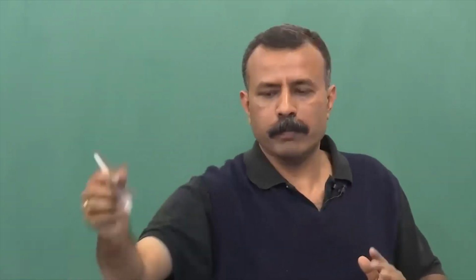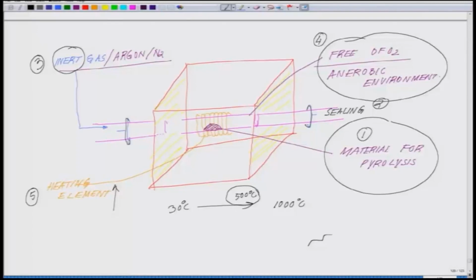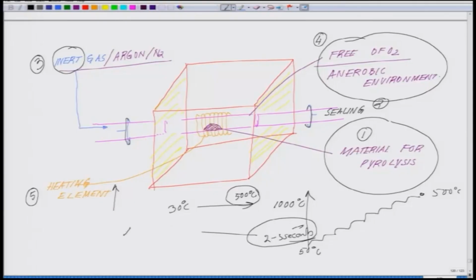So, exactly similar to that, you can really jack up the temperature like soup. Instead of having the temperature curve like this, say for example, you are increasing the temperature stepwise, okay. You are reaching to this point. Say for example, if this is 50 degree centigrade, this is 500 degree centigrade. Over a period of multiple cycles you do it, over say half an hour you go. Whereas you can actually reach it like this, boom, in 2 to 3 seconds, okay. Such processes where you are raising the temperature like this is called flash pyrolysis. And it has its implications, I will come.